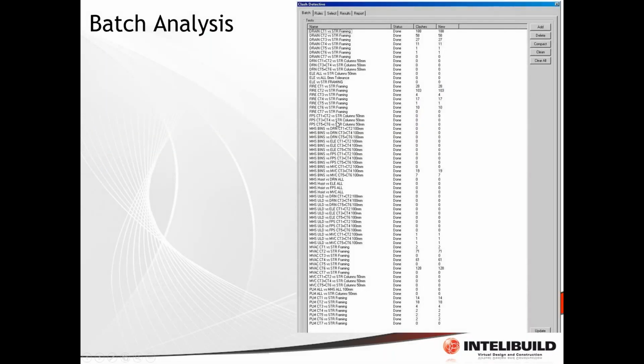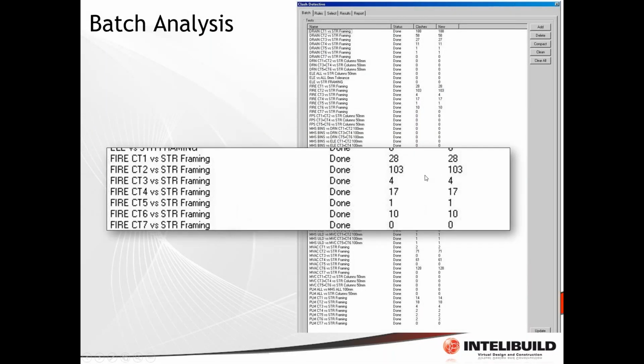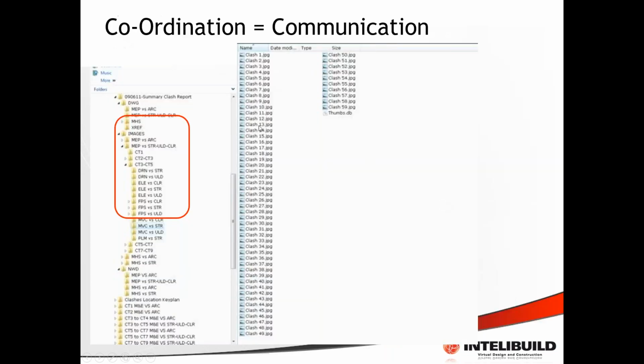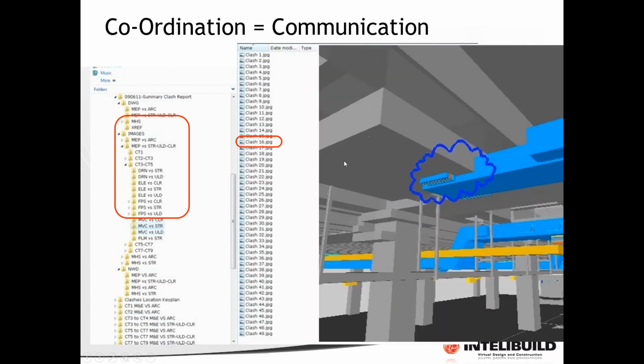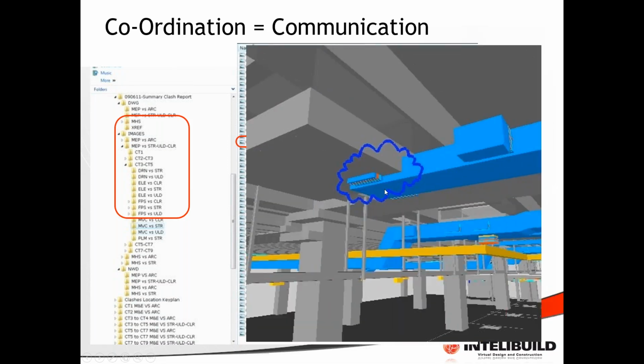And this is how you can use the software. This is Navisworks. You can run automatic clash detection. It'll find all the issues. You can categorize all those issues, and then you can see what they look like. So you can see, well, there's a problem. There's ductwork clashing with some concrete. We've got to get that fixed.